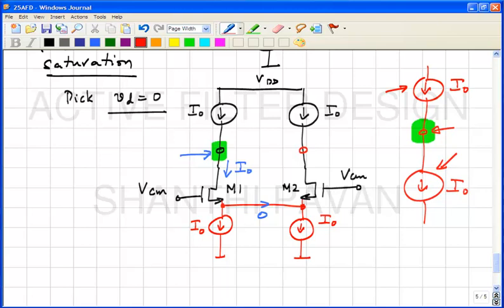So, if you have a node and the total current being pushed into the node is exactly the same as the total current being removed from the node, then there is no net charge accumulating on the node, therefore, its potential remains constant, correct? So, if two equal and opposite currents are incident on a node, then the node potential remains constant.